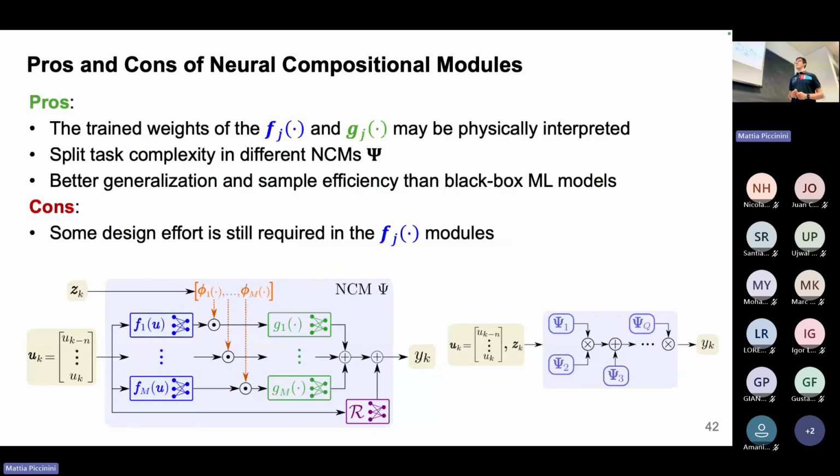I want to say one thing related to this. We present here in this order. In the order of the input function is always the nonlinear function and the output is always the dynamics function. But we have at least one example where we do the opposite. We swap the input, so the nonlinearities and the nonlinear function, because maybe physically the nonlinearity merges with the output of the dynamics, not the input of the dynamics.